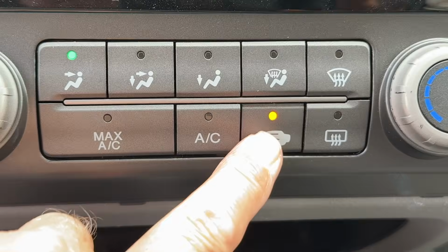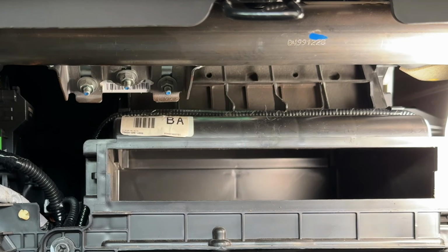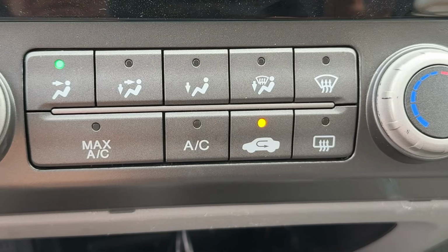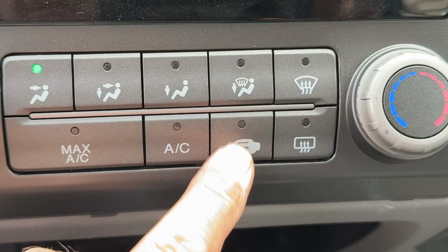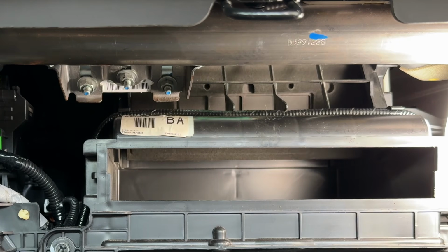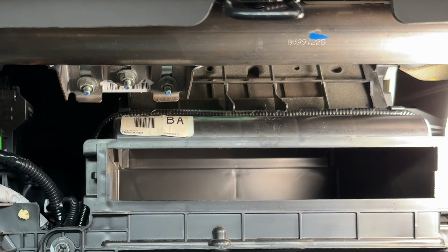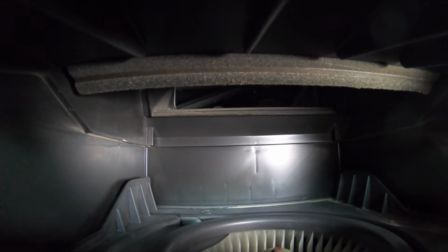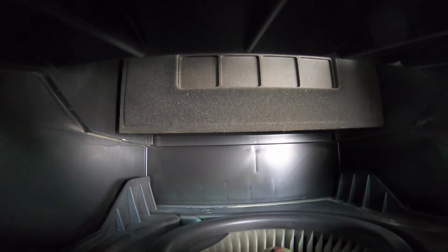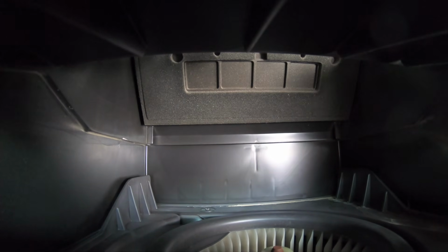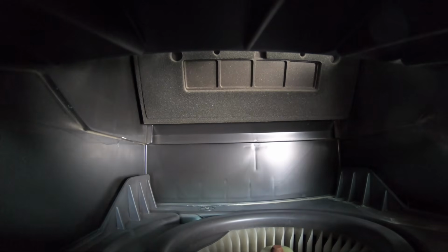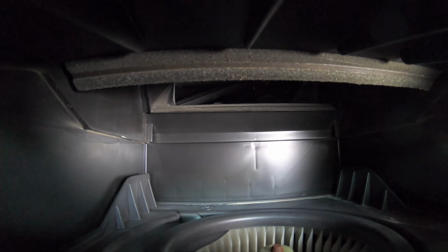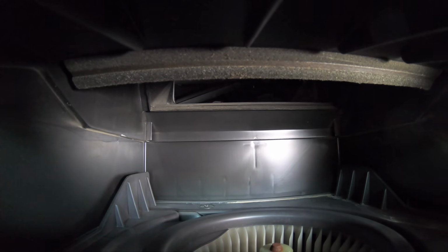Now once I push the recirc button, that flap closes off outside air, and now you're recirculating the air that's in the cabin. Now if I push that recirc button again to take it off, the flap opens, and now outside air is coming inside the cabin. Here's a view from inside the air distribution box. Push the recirc button, the flapper closes off outside air, now you're recirculating the cabin air. Push the recirc button again, it'll open the flapper to outside air. This air is going to get filtered through the cabin filter. The recirculation system's pretty easy to diagnose.